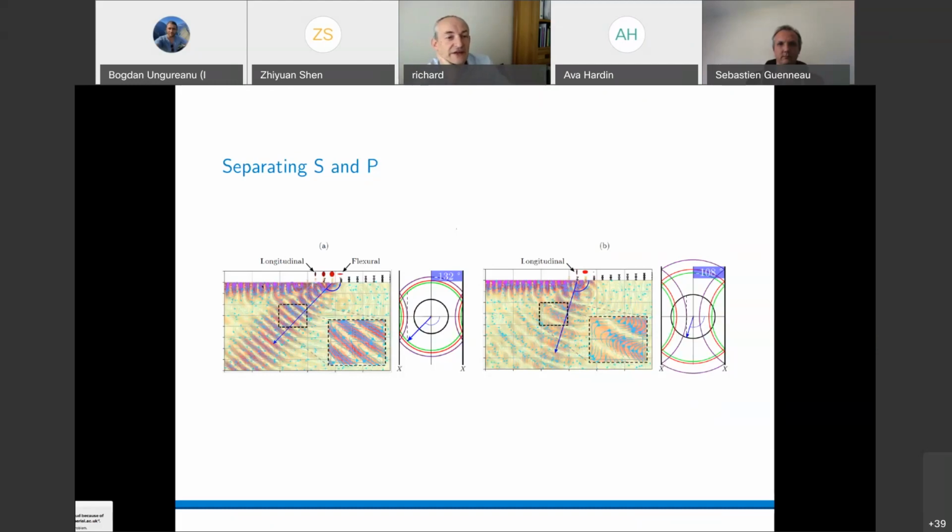In this case it's longitudinal, but then it becomes flexural when we play this game. We draw our dispersion curves, we get flipped back. It couples into the shear wave. It can't couple into the compressional wave because this contour does not intersect that vertical line. So we will only get shear waves back, and they will be directed back. And that's exactly what the simulation shows.